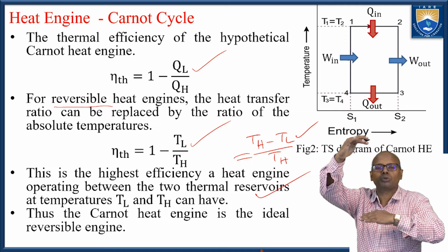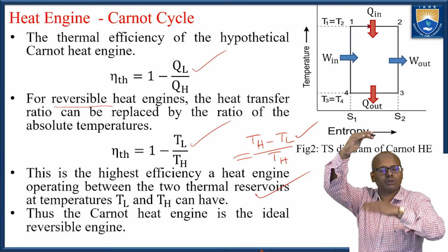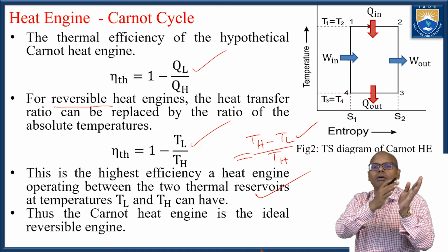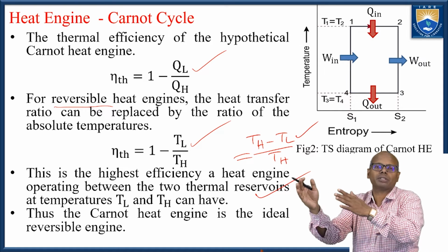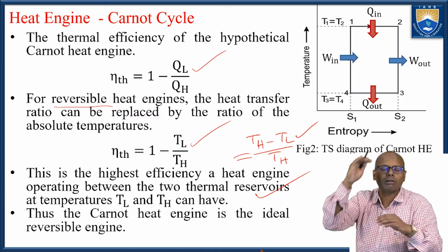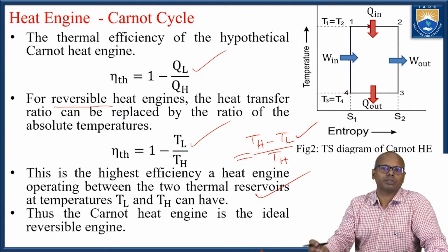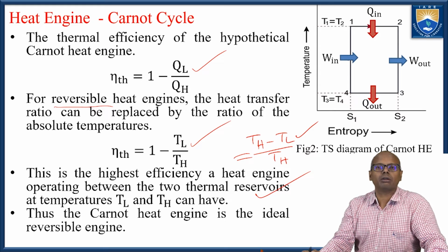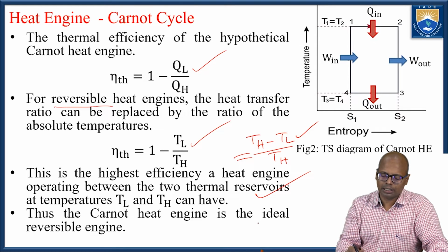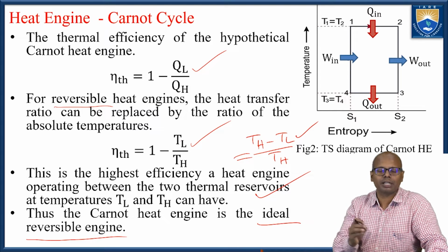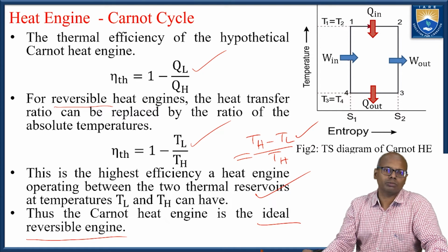Suppose I have two temperature reservoirs, high temperature and low temperature, and I have many engines with me. When I compare the performance of all the engines, the Carnot engine, if I can develop it, will give the maximum efficiency. So the Carnot engine is considered the ideal reversible engine for reference of all types of heat engines.